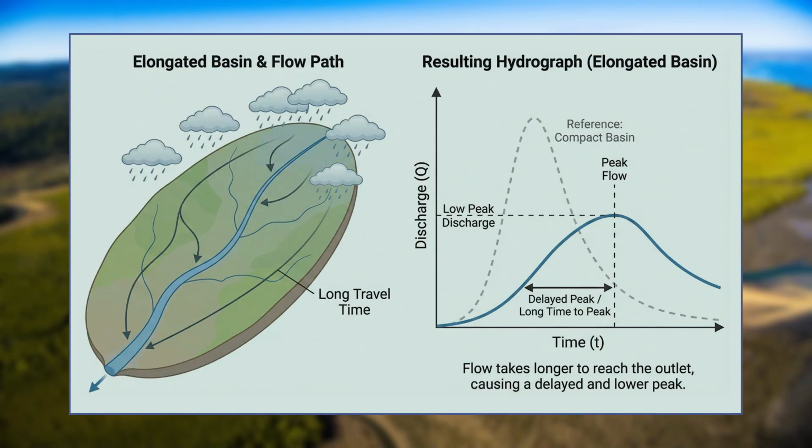This is mainly seen in the Himalayan rivers, which have steep gradients and circular shape. Conversely, in elongated basins, flow takes time to reach a river channel, causing a low peak. It also depends on the runoff contributing area in a watershed. For example, in urbanized watersheds, runoff will be very high, while in the forest watersheds of same size, the runoff